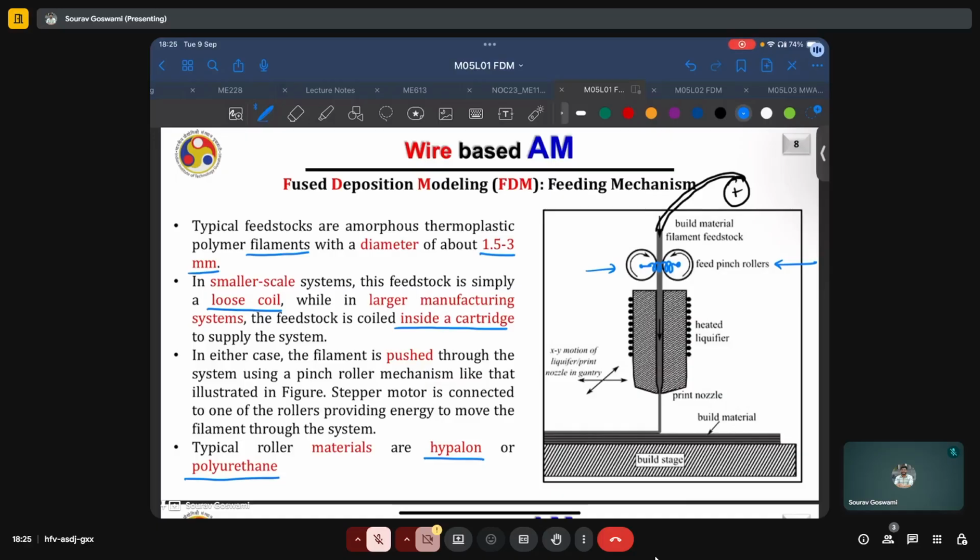So what we can do is, there will typically be some specified tension or torque range for these rollers. We'll only tighten them within that specified or recommended range, and then feed some known length, say 5 centimeters of wire, through these rollers. Then we would cut the wire very near to the nozzle, and check how much of the wire is getting extruded. If this value is very close to the desired value, we know that the calibration is fine and we can trust the feed rate from the rollers. But if it is off by a large margin, we'll need to calibrate again.